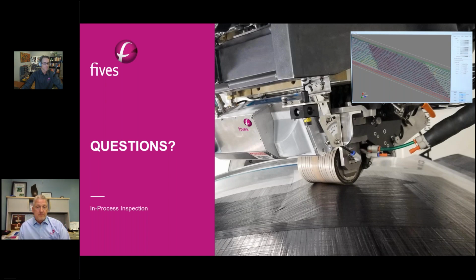Yeah, so the contour basically causes the sensing surface to be closer or farther away from the part, right? So we call it depth of focus. Line laser triangulation and regular cameras have a fixed depth of focus, which is defined by the optics. Our depth of focus is 2 to 3 times what line laser triangulation is. So we have 25 to 30 millimeters of wiggle room, where the surface can get closer to us or farther away and we don't lose sight of it, and we can still take great measurements along with being able to be off axis.